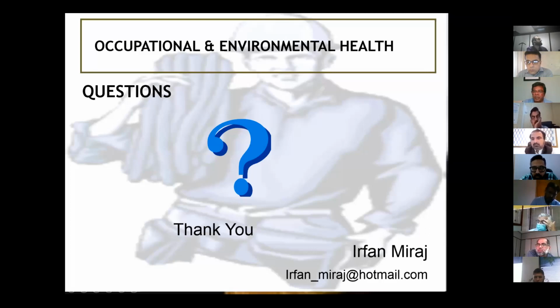So it's not prohibited. Go ahead, use those sheets, but help those workers, have some mercy on those people who are preparing, who are cutting those. Even if they have some wetting arrangement, don't let the dust fly away. Put some exhaust fans. That person was cutting sheets outdoors, which is fine, but don't have kids standing right next to you. Apply some water, have some vacuums attached to your cutting equipment so that you can suck that dust and not allow it to spread.